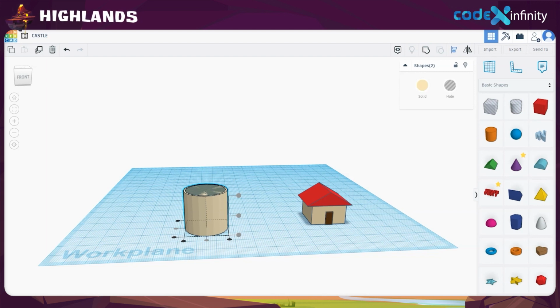You see those black dots at the center of all sides have blurred? That implies that our alignment is correct and we don't need to make any further modifications. The black dots appear when we click the Align, as you know. If the black dot at the center of a side is blurred, that means the alignment is already precise. But if it is not blurred, we must click on the center dot of the particular side that we want to get the alignment to be perfect.